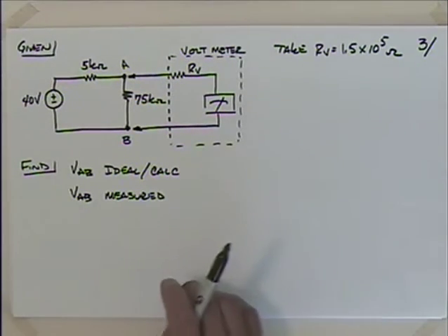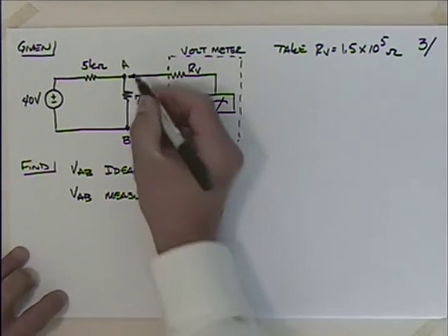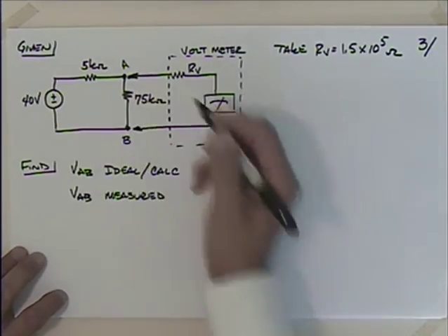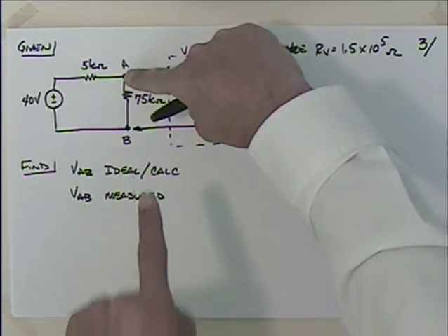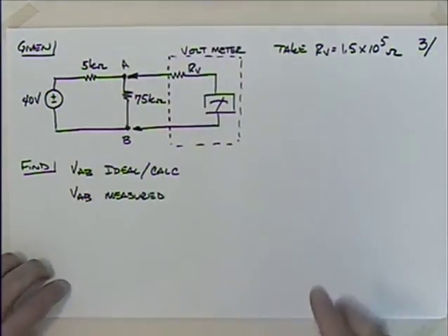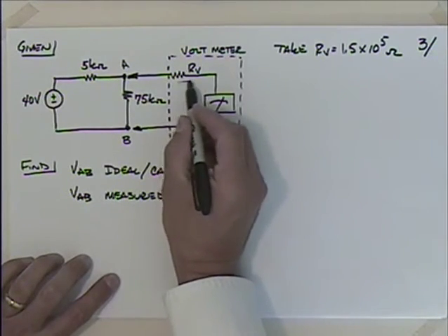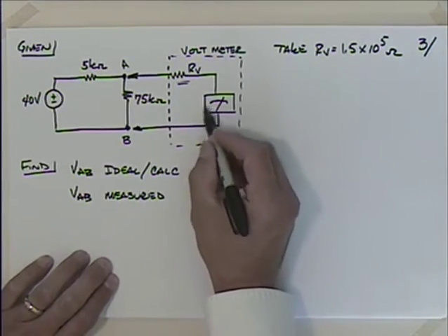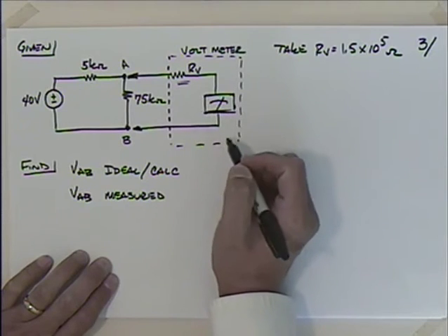So that's the circuit itself, and then we say, well, what happens if we come along and we measure this? We put this voltmeter here. That's where we take the probes of the voltmeter, put one there and one right there. What's that really doing? Well, inside the voltmeters, there's some internal resistance, and there's this meter, which is essentially just a coil.